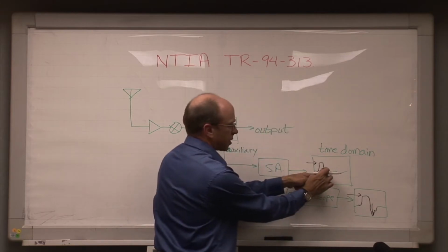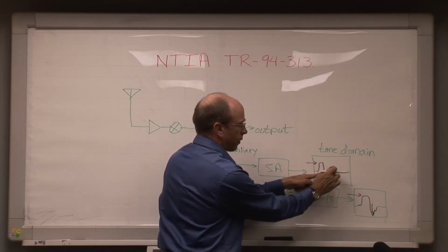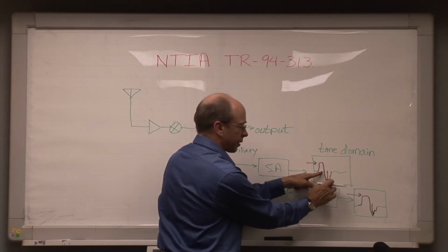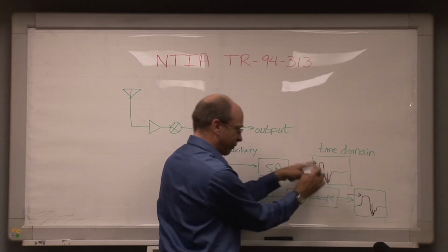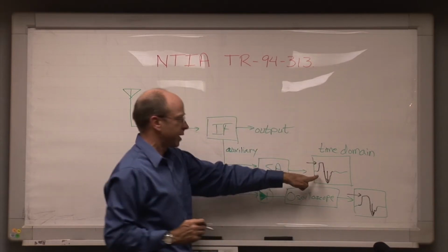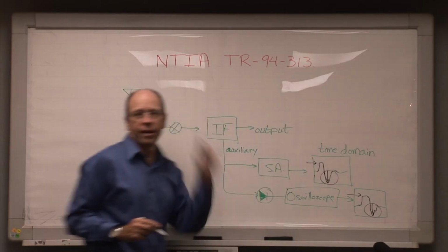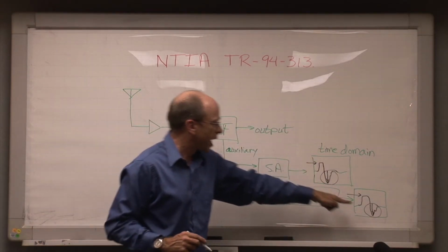and it takes some non-zero amount of time for the amplifier's gain characteristic to recover after it's been hit by the pulse. And the reason that the receiver is suffering degradation is the receiver's losing data while it's being hit by the pulse first of all, and while it's recovering.